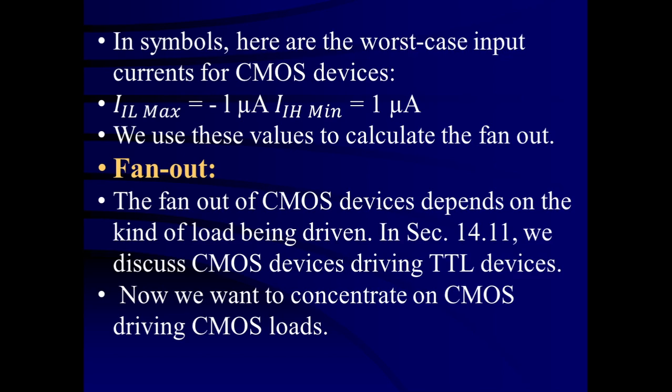What is fan out? How many CMOS loads can the driver output of a CMOS drive without destroying any CMOS load or disturbing its switching action? That is called fan out capability. The fan out of a CMOS device depends on the kind of load being driven.